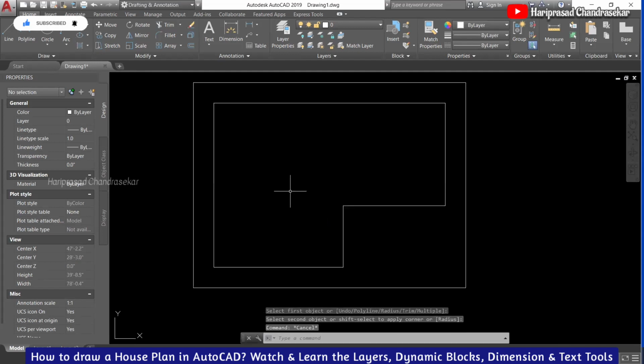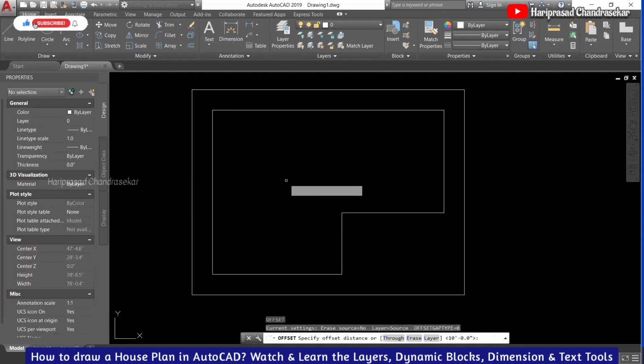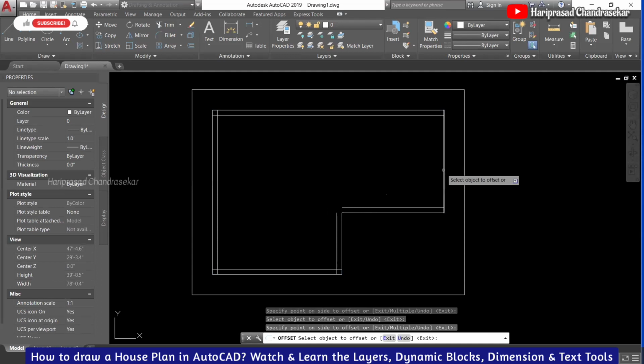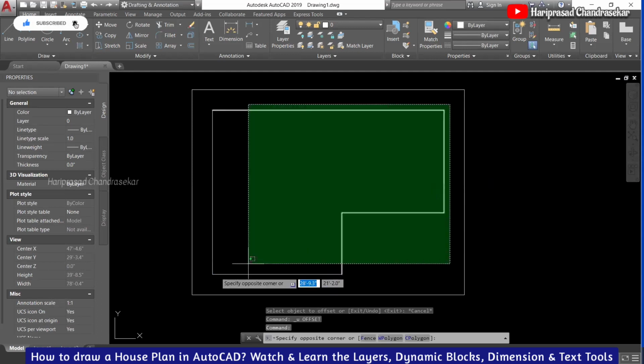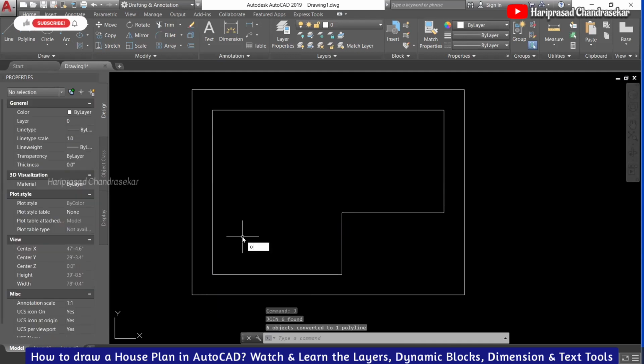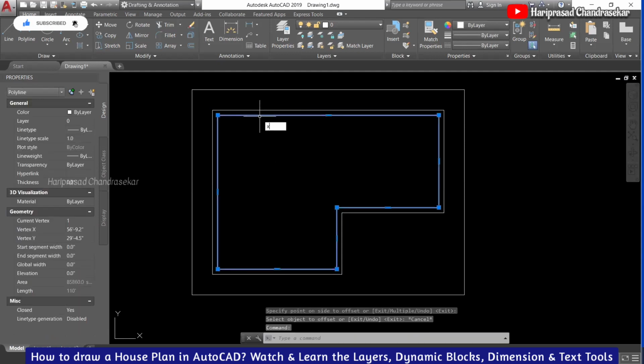Now we can start building. See, first you are supposed to put a 9 inches wall. So I'm just putting 9 inches wherever you have the walls. Actually, we can also join it. What we can do is, otherwise, you just select everything, Join them, J, enter. So within a single click, we can get the offset of 9 inches. Now we can just explode this one.